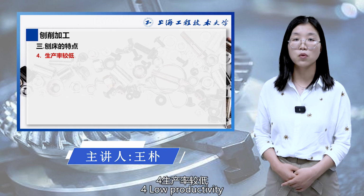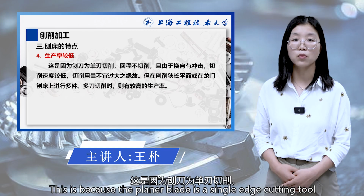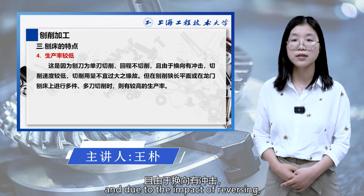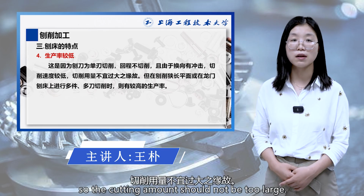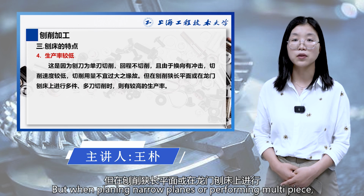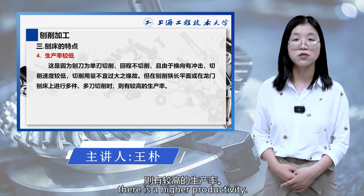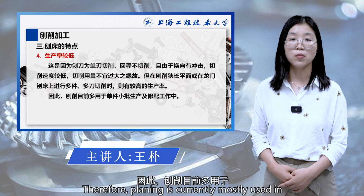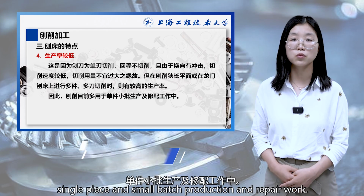Fourth, low productivity. This is because the planer blade is a single-edged cutting tool that does not cut on the return stroke, and due to the impact of reversing, the cutting speed is low, so the cutting amount should not be too large. But when planing narrow planes or performing multi-piece, multi-blade cutting on a gantry planer, there is higher productivity. Therefore, planing is currently mostly used in single-piece and small batch production and repair work.